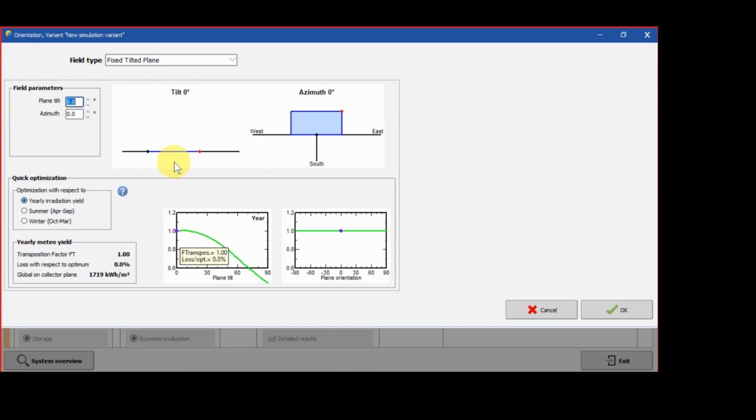Because when there are objects, or for example water from rain hits the module, it's going to stay on the module, right? If we tilt the module, then if there is any light dirt and so on, it can be washed automatically by rain. That's one of the advantages. But actually, the important thing about tilt angle is because we want to optimize the angle of the module so that we can get the maximum amount of sunshine.